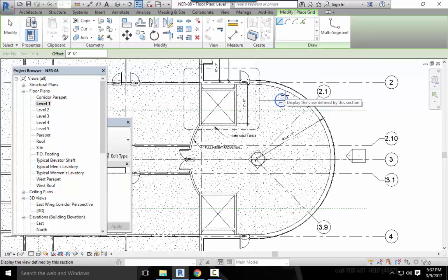Item 3, on the draw panel, click the pick lines button as shown in figure 8.19. Pick lines, okay. Type an offset value of 6 inches. So just like we offset lines or anything else, we can offset grids. And the reason for this is we really want the columns to be inside that wall. Or on the inside, on the interior of that wall. Inside the wall is a bad term.